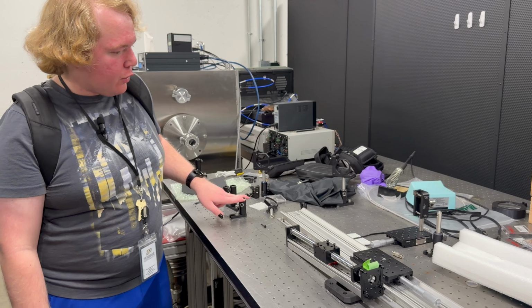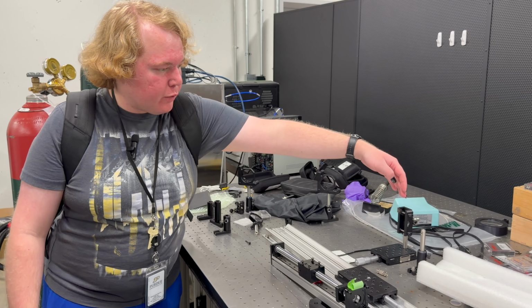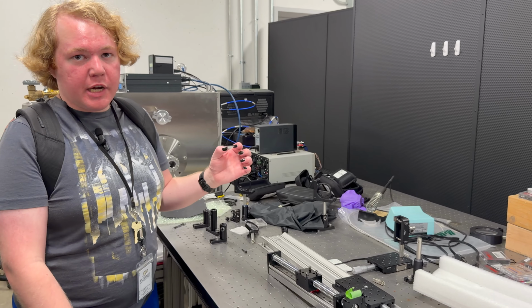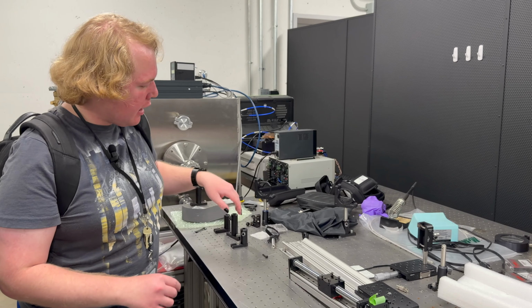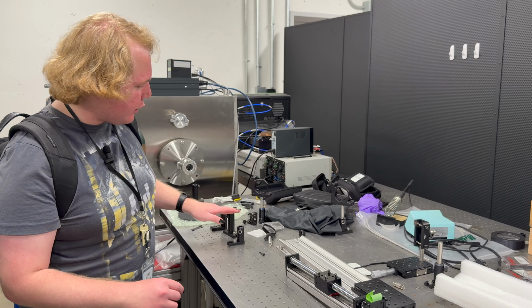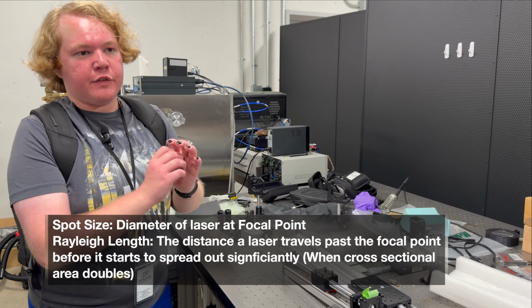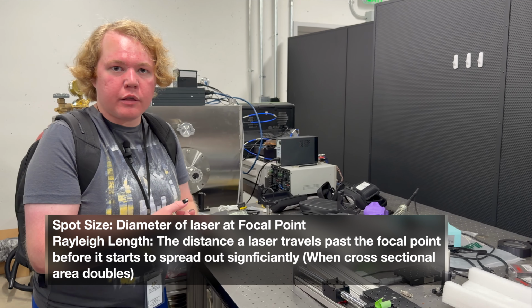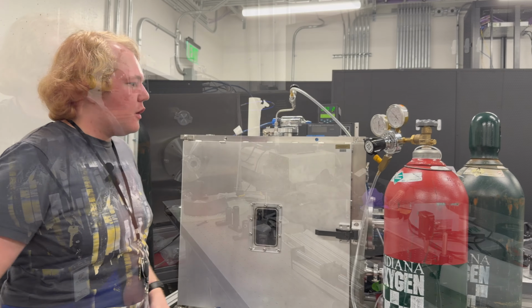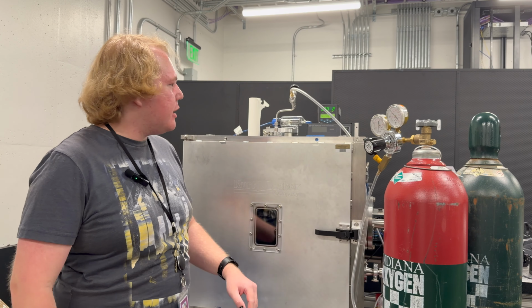And then as well, over here we have two flip mounts with mirrors on them in order to redirect the beam. We don't have a mirror in this one at the moment, but this one would be used to determine our beam diameter, which is the total thickness of the beam before it is passed through the lens. And then we would have one after the lens focusing area here with another mirror onto a beam profiler, which we would use to figure out what our actual spot size is, as well as the beam quality and Rayleigh length of the laser.